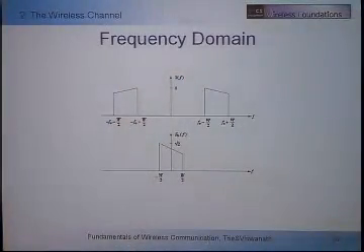And this picture shows you why we have to look at complex numbers in the frequency domain. What we're really doing is that we start with a baseband signal, and then we shift it to the passband. You can see that in the passband, you have conjugate symmetry. It's a real signal, of course. We may want to think in terms of complex numbers, but we're dealing with the real world, and therefore we send real signals.